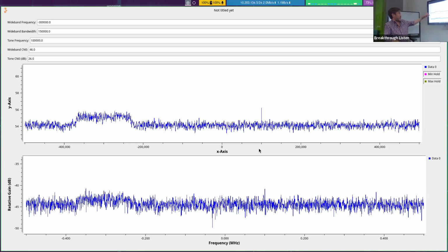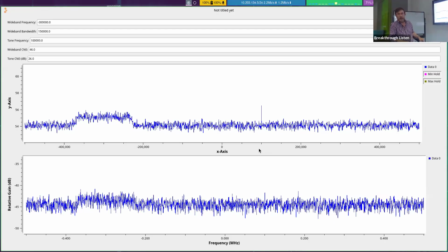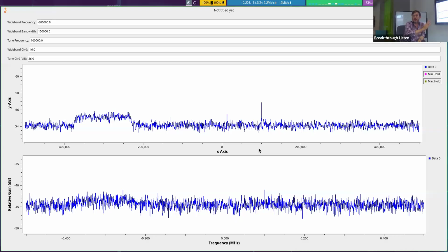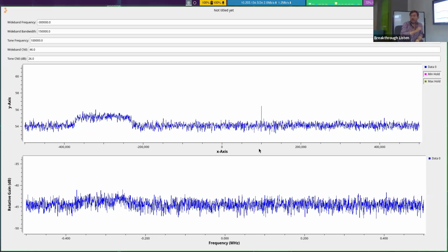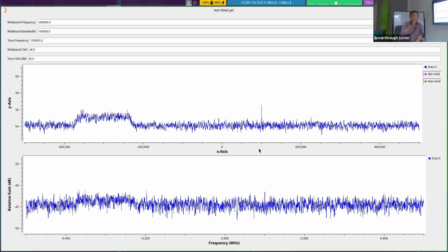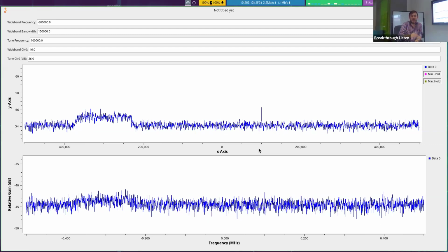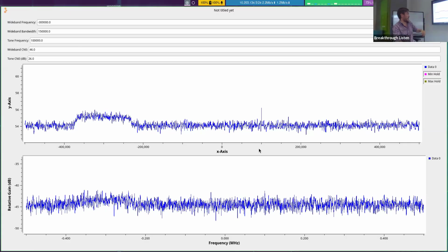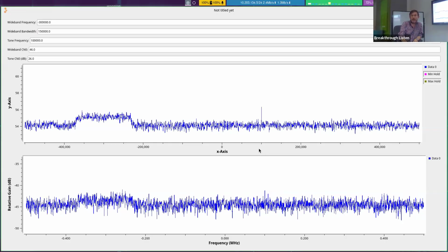The downside of that is, if you look at the narrowband signal here on Daniel's plot, if that narrowband signal wasn't constant in frequency but drifting due to the Doppler effect, for example, over time, and it drifts more than one channel in the course of one integration, then it's going to get smeared and you lose power, because it turns into something that looks more like the broadband signal on the left there.